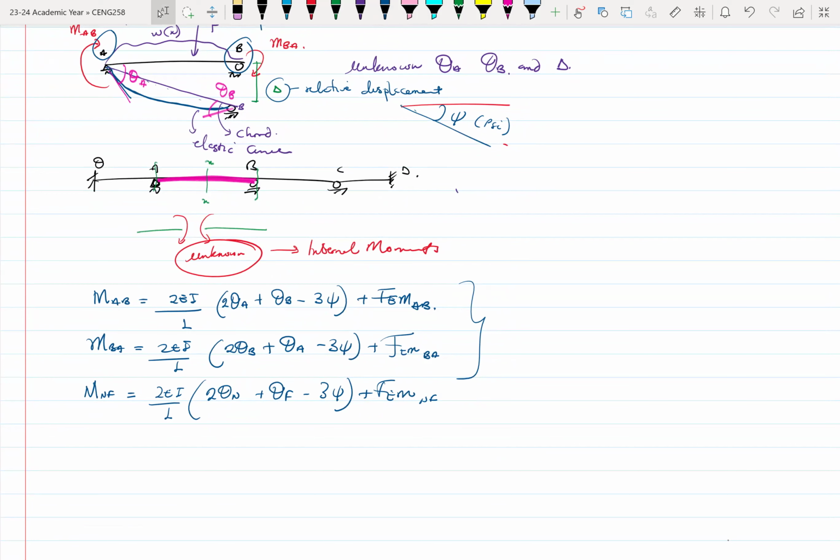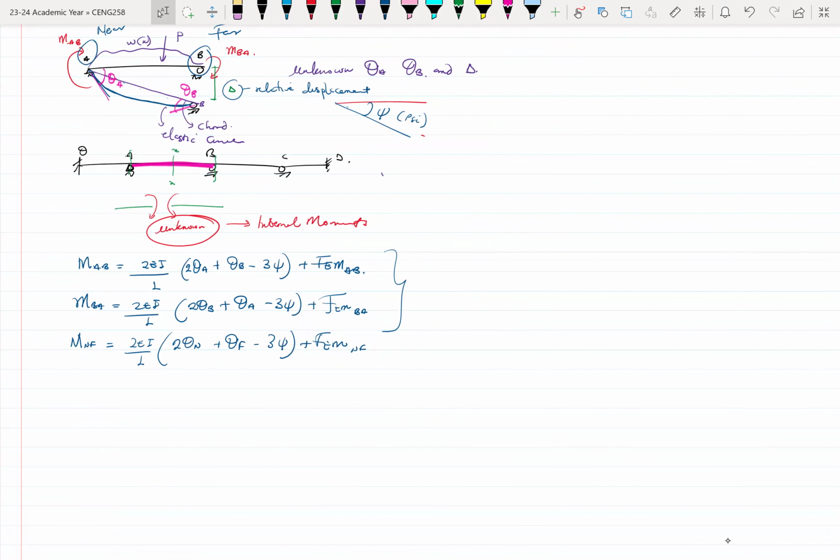The general idea is to take these equations, use the principle of equilibrium, the force deflection or displacement relations, and also use the compatibility conditions to formulate equations which we can use to solve the structure. First, always identify the DOFs.